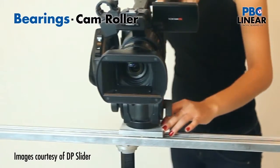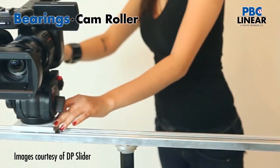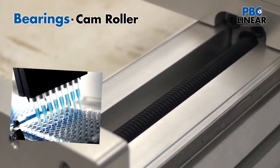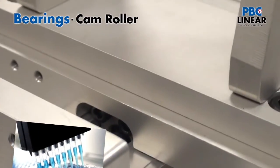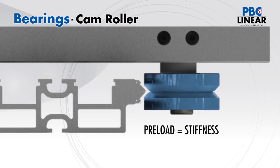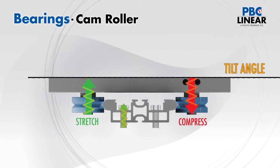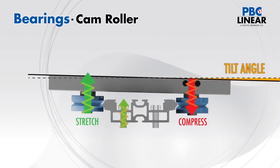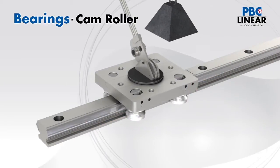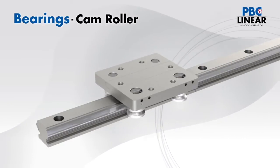For example, camera sliders need very light preload and very low friction movement to achieve smooth, effortless motion. But highly precise measuring applications require greater preload, resulting in greater stiffness and rigidity. Not only is the elimination of play an advantage of preloading, but also minimizing the effects of deflection. Beam or structural deflection will be dealt with later, but first recognize that the components within a bearing system are also subject to deviation dependent on loading.